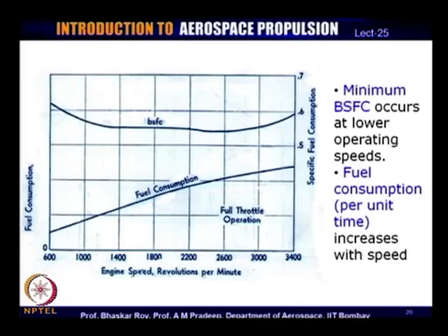So, if you keep an eye on the efficiency of the engine, then you would probably like to operate somewhere at slightly lower values of engine speed, and we have seen that at one of these lower values you also get a high torque. So, high torque, BSFC, fuel consumption, and power production are 4 different parameters, and engine operators have to keep an eye on all of them while operating the engine to find the best balance during the various courses of operation of the engine.